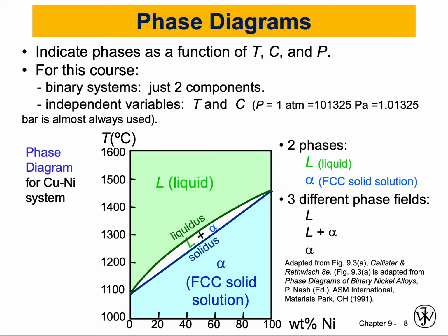If you look at this phase diagram, you can identify regions. And if you remember from the previous one that was about the sugar and water, we had only one curve, just like this was the solubility curve, right? Now I have two curves. This is called the liquidus curve, and the blue one is called the solidus curve. And we're going to look into these regions carefully.